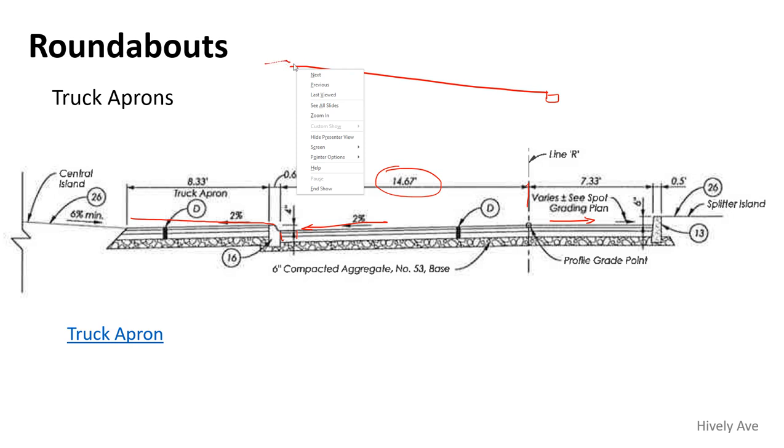Here's our island in here. And then all the water goes to the outside. That's, in this case, if it's also a 2% slope, that would be like a negative 2% super elevation. So cars have to go a little slower on it, which is what we often want. We want them to go slower, right? So with this one, you cross over that grade line and to the inside, and then you can go a little bit faster because you've got a positive super elevation.